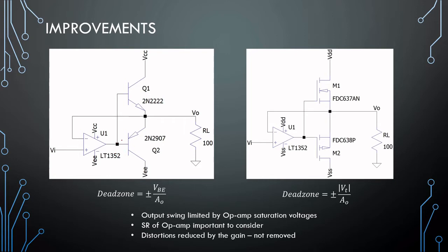Okay, but since we are building a driver circuit, we use the op amp in a buffer configuration, and the only thing that it does is, op amps in feedback tend to linearize distortions. So the dead zone that we're having is a VBE voltage right here, or technically 0.5 volts, but let's go VBE divided by the gain of the operational amplifier. So with infinite gain, this distortion can disappear completely. It will not disappear completely, but roughly.